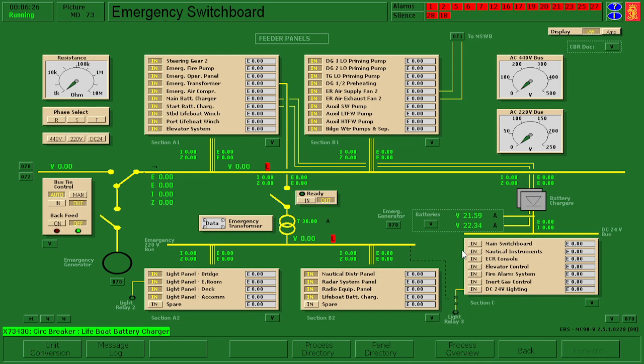If you start up your generator without any power fed to these systems, when you close these circuit breakers, the generator is going to have to throttle as you're closing these, and you're definitely going to put in a lot of strain.